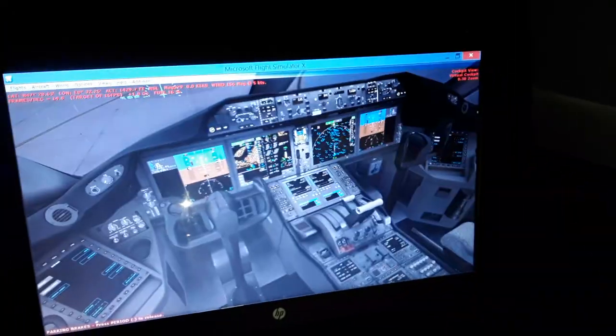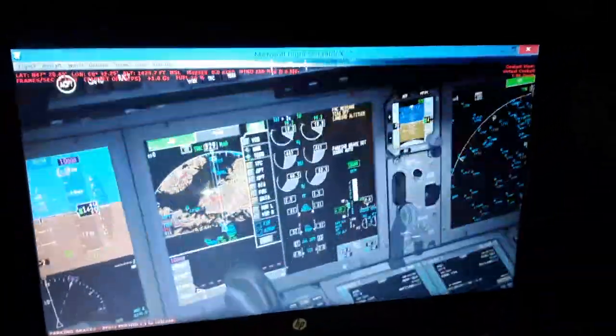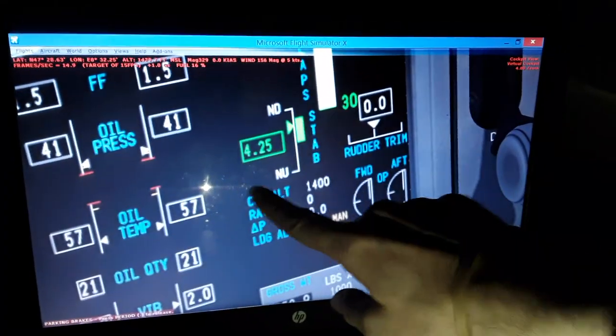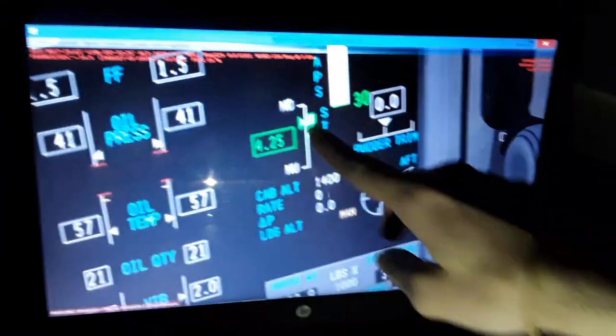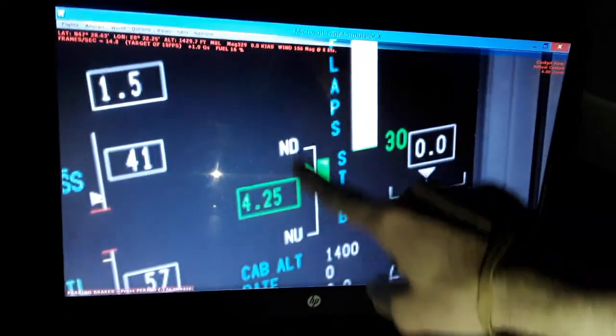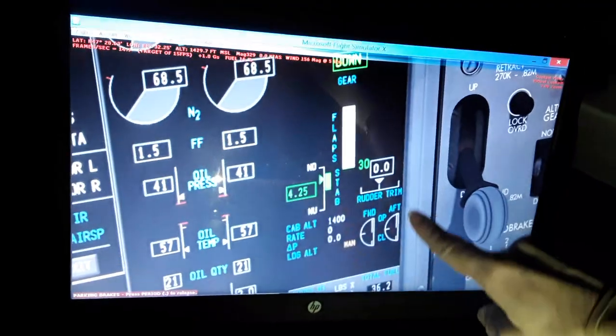with the tiller. Also we have here, you can see the stabilizer trim position is displayed over here in this switch. Stabilizer trim, we have the stabilizer trim. You can see the position right now is 4.85 degrees set for takeoff. We have the maximum and the minimum limit. The rudder trim, the flaps, also the cabin pressurization of the aircraft. You can see it displayed here.